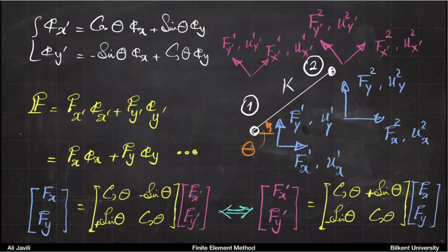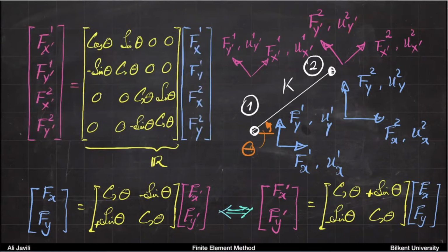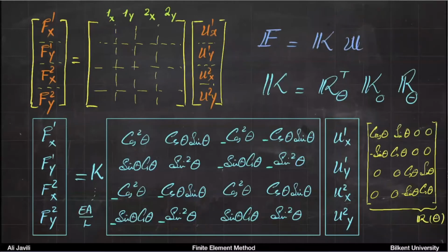We mentioned that we know how to compute the stiffness for a truss in the white coordinate system, or in this picture, maybe in this pink coordinate system. What we need to do is rotate that into the blue coordinate system, and we do that through this rotation matrix. We rotated the forces, we rotated the displacements, and by rotating forces and displacements, you end up with 2 rotations which should be multiplied with the stiffness to give you the global stiffness in a rotated coordinate system, or in this case the elemental stiffness in the coordinate system. And you get this one. This is the rotated stiffness, and you can see clearly it's 4 by 4, and it has this immediate dependence on the angle theta.